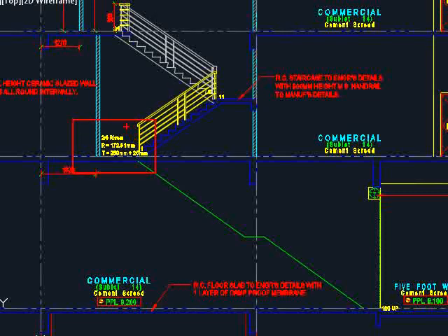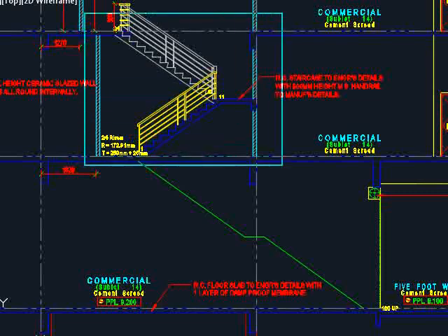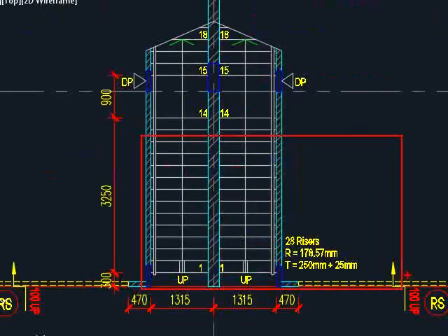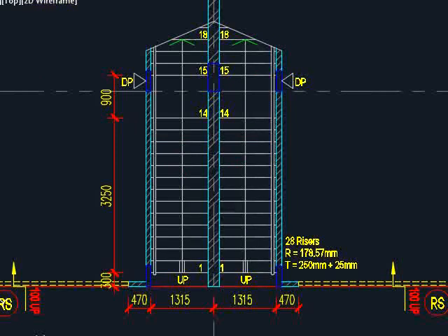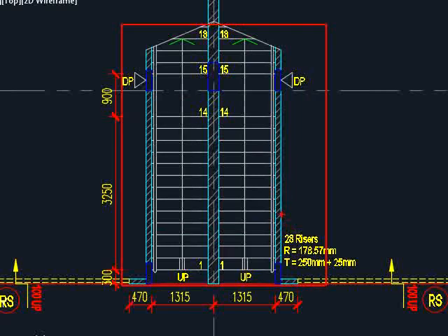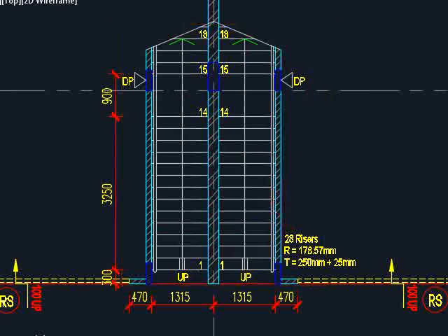The details are given and the dimensions are given. In fact, this part is also meant for the staircase, although it is not clearly drawn, but the details are given in the architectural floor plan. If the exact dimensions are not properly illustrated by the cross-sections of the building, you will have to sketch it yourself in accordance with the details given, to be closely checked side by side with the plan view as given by the architectural floor plan.